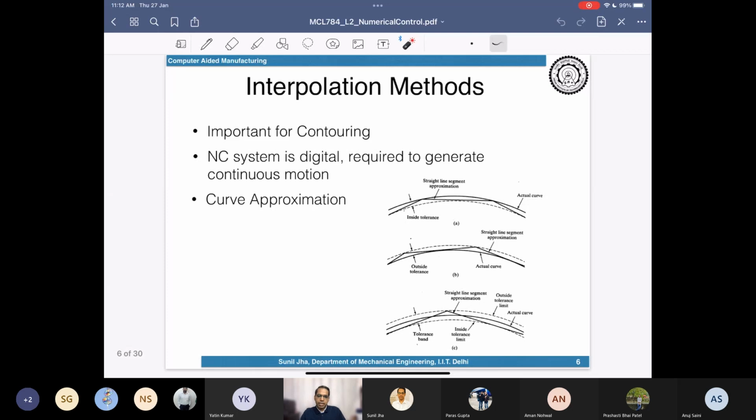So in that case, the different geometries are created with the help of the interpolation methods. You normally see that when we talk about the part program, we only give the start coordinate or the end coordinate or certain parameters actually. Now, based on that input, the intermediate points are generated by the machine controller, because we are not specifying all those points. For example, if I have to do a linear motion from point A to point B, we will only be specifying the 2 points. Now, how the machine will make the motion happen from point A to B is computed by the controller, and the machine controller will then calculate all those intermediate points based on the type of interpolation you look forward to.